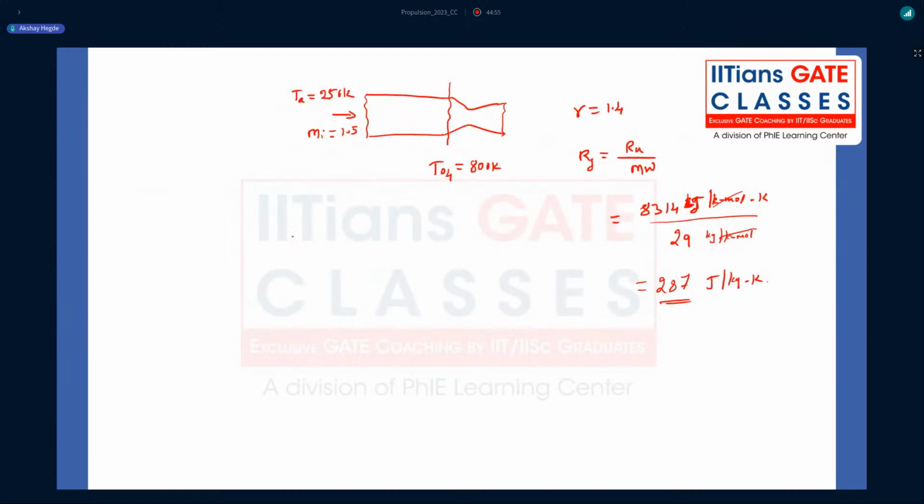For a turbojet engine, we derived the propulsive efficiency to be 2 alpha divided by 1 plus alpha, where alpha is Ci divided by Cj. Ci is the incoming velocity and Cj is the exhaust jet velocity. Propulsive efficiency becomes maximum when alpha is 1, that is when Cj is equal to Ci, giving 100% propulsive efficiency.